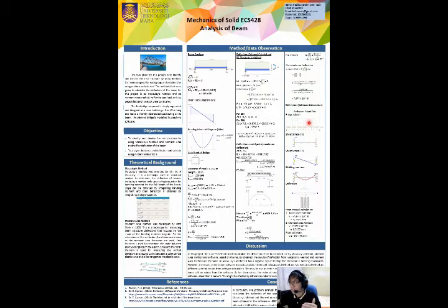Next, the shear stress in X direction is equal to 0, while the Fy, what we gain in the software, is the same as the manual calculation, which is 1148.4. Next is the bending moment. The maximum bending and deflection occur at 7.5 meter, half of the beam length, which is 15.